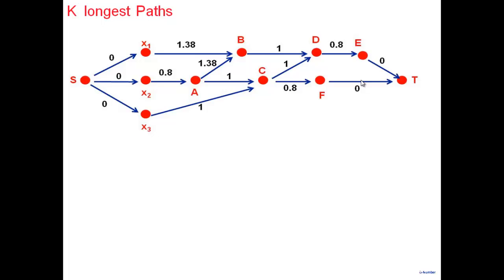How will I take those decisions? I must have delays. Where are these delays coming from then? See, delay will eventually come from where? Logic has no delay in it. A gate has no delay. It's a logical operation, a Boolean operation. Delay only comes about because you have a capacitance and you have to charge and discharge.